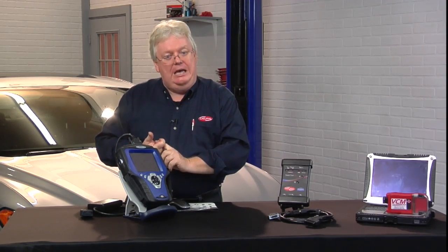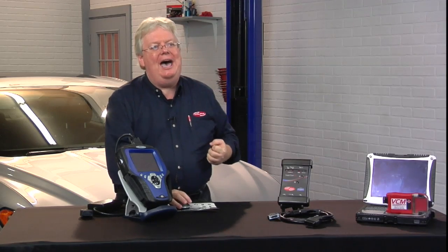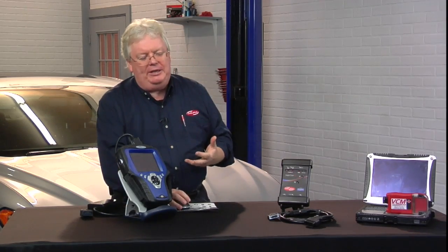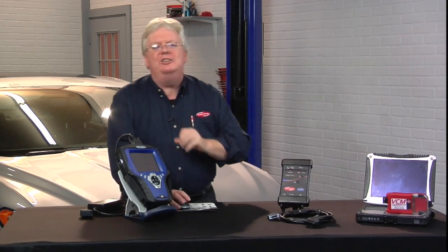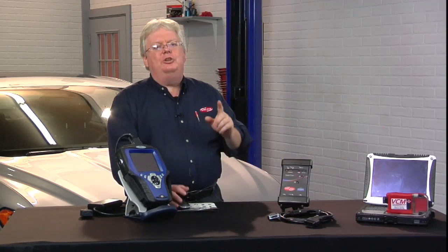And it does say it's failed, and the ECU, the electronic control unit, in this case is $10, and that would be the PCM in this case. So that's its ID on the data bus. So that's how you navigate on this particular scanner. I'm going to show you on a PC scanner how you navigate with our Delphi unit. So practice with your own and see how you get around. So let's go ahead and do that now.